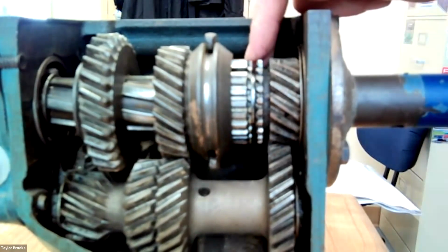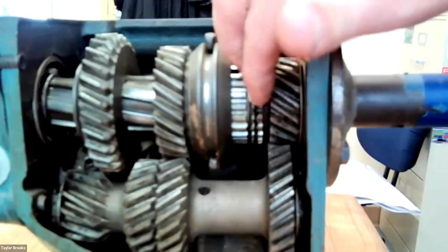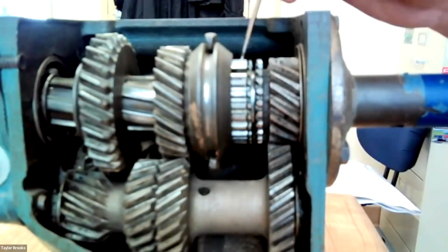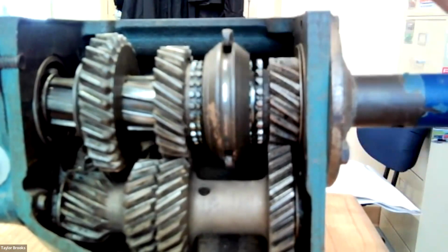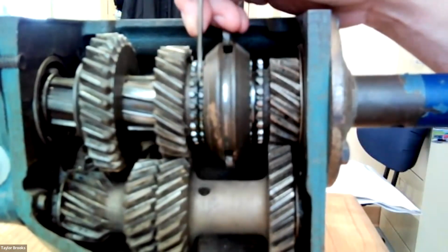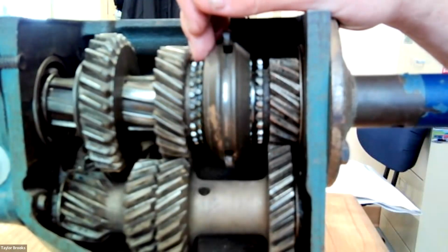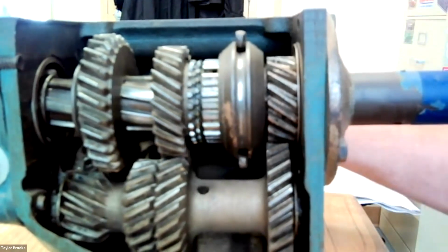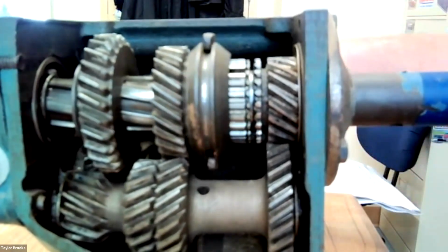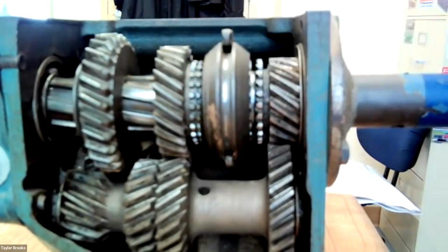So we can see with it in second gear, the blocker ring is free to rotate, and it can rotate independently of the speed gear and of the hub itself and the slider. But as I engage the slider, so we have second gear's blocker ring right here, the teeth will line up. So even if I get them misaligned, like that, if I shift slowly into second, you can see everything start to line up. And when I move everything, everything's in line.